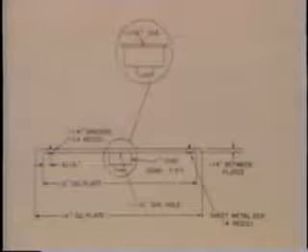The plates are spaced 1/4 inch apart in order to prevent the velocity component from reaching the 1/16 inch diameter pickup orifice. Airflow perpendicular to the pickup orifice is near laminar, greatly reducing unstable reference pressures associated with turbulence at or near the sensing location. In addition, a hollow 1-inch diameter pipe stand used to support the sensing head will act as a dampening chamber to further dampen sudden pressure changes caused by wind gusts, etc.